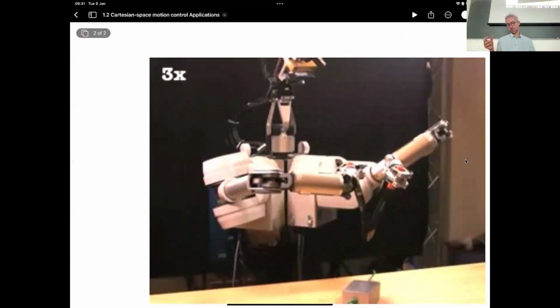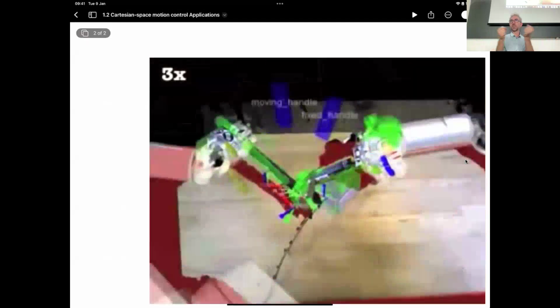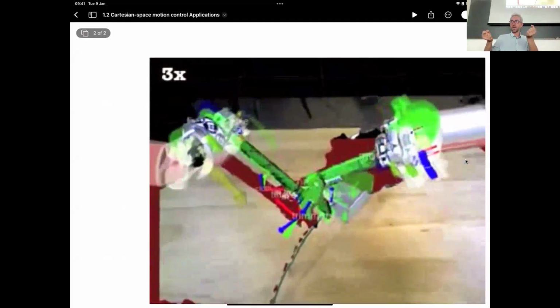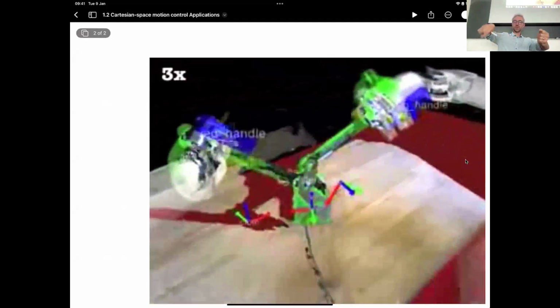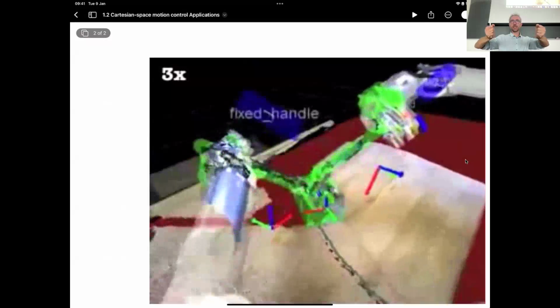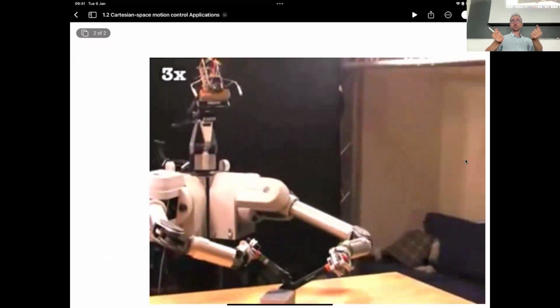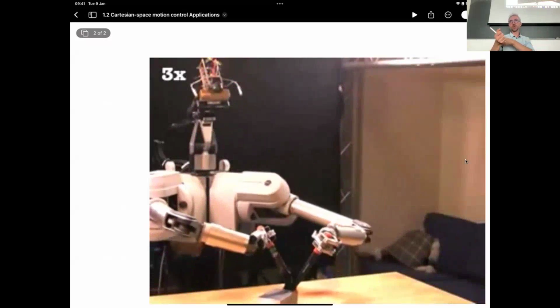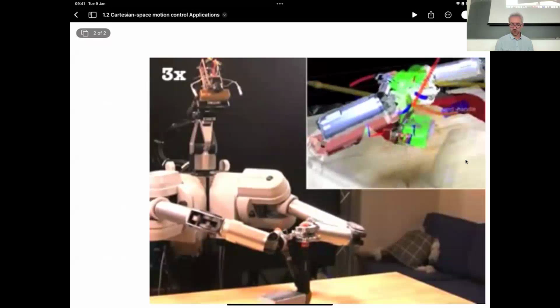But this is, yeah, here the main challenge is that you have a bimanual task. So the robot has to use both hands, which is creating a closed kinematic chain, which is pretty tricky because you can apply very large internal forces without realizing it, which might end up breaking the robot or burning a motor if you don't pay attention to that.